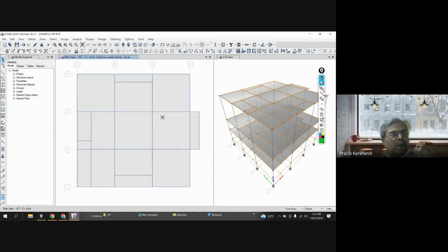Yes, sir. And also remember one thing: in civil engineering, nothing is exact. Everything is approximate. You say that the self weight of reinforced concrete is to be considered at 25 kilonewton per cubic meter. That is your assumption. It may vary from 24 to 25. So which one is correct? Everything is correct and everything is approximate. And that's why I always say that in civil engineering, we are not interested in getting the exact answer, because the exact answer nobody knows, right?